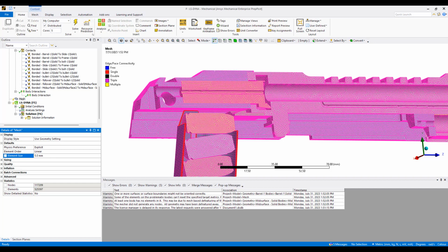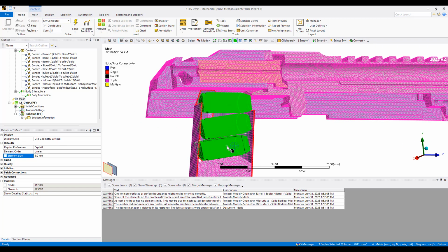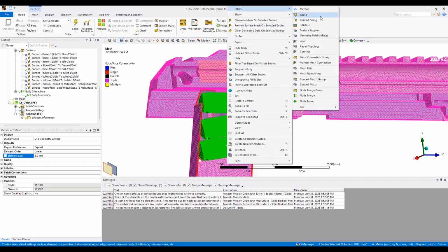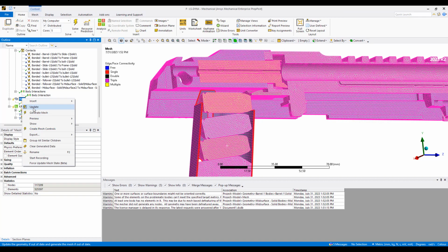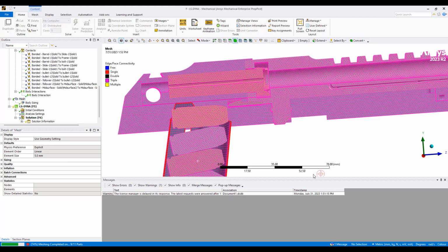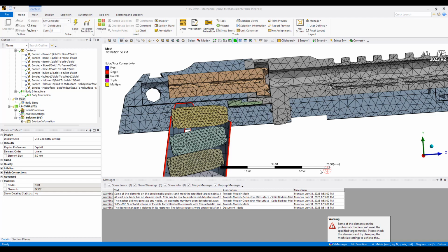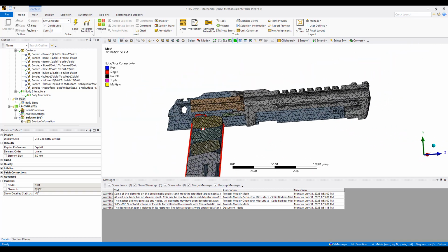So I'm going to increase the size of the mesh globally to a size of 5, and then I'm going to make the bullets a little bit more refined. So these will have a sizing of 2. I'm deliberately getting a lower quality result so that I can get results quickly. So much coarser mesh, but now this is only a few thousand elements, so it'll run very quickly.